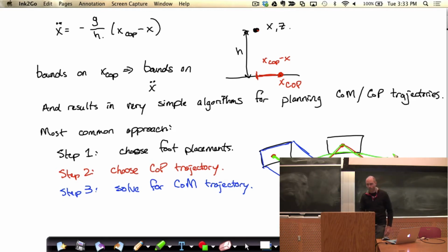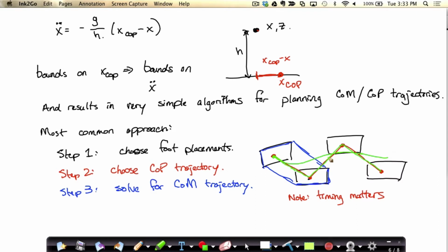And ironically, walking faster can be easier than walking slowly because you have to move your center of mass a lot less, right? We actually saw that in the DARPA competition. Our controller was kind of struggling to walk slowly, and then we just ratcheted up the speed, and everything got a lot better. And then at some point, the simulator stopped working. The simulator we were given, and the robot's legs started deflecting into themselves, and we had to stop. But it was kind of fun to see how fast you could make it walk.